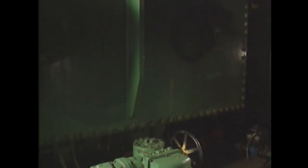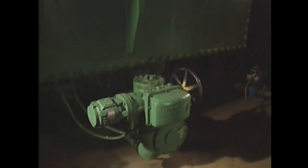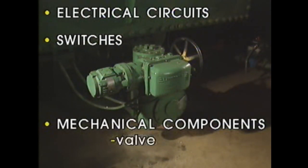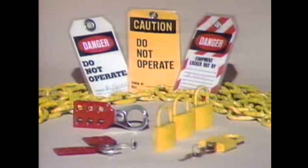When the control room reports that a motor-operated valve isn't functioning normally, a technician will have to troubleshoot to find out whether the problem is in the electrical circuits, the switches, the mechanical components of the valve, or the mechanical components of the motor operator. It's especially important to remember that electrical problems within a motor operator can create an electrical shock hazard. The technician has to take the valve and the motor operator out of service and place them in a condition that allows them to be worked on safely.